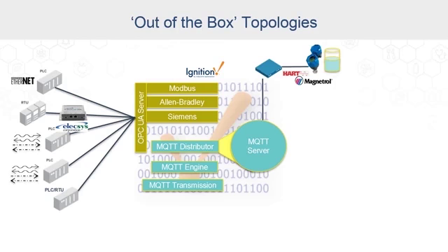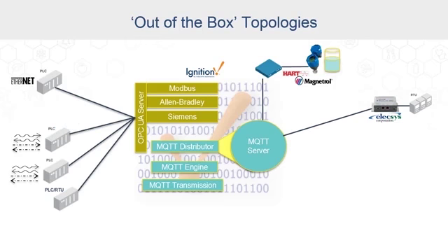Lantronix manufacture a very interesting edge of network product that's able to provide terminal server ports. So in a migration strategy, I could take an edge of network gateway that implements MQTT, and I could continue polling with my OPC UA server, say Modbus or Allen Bradley or Siemens protocol, but at the same time, I could start moving my polling locally in real time and then publish any PLC register that changed in my MQTT infrastructure. I can run in this mode until I'm very comfortable with MQTT, and then I could slowly phase that out.